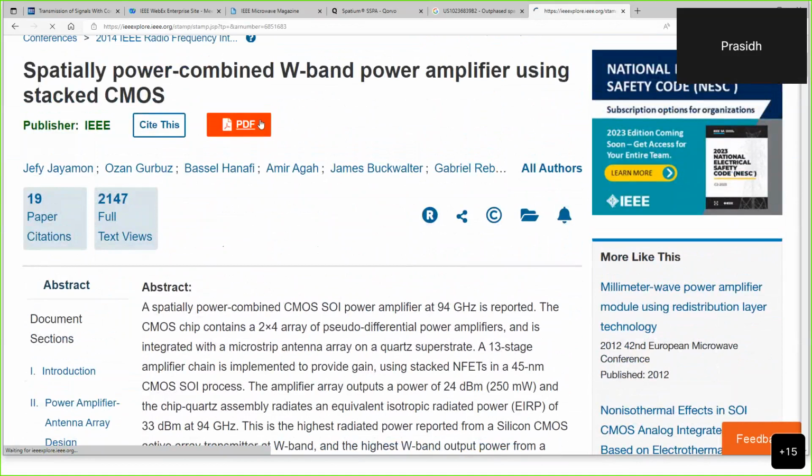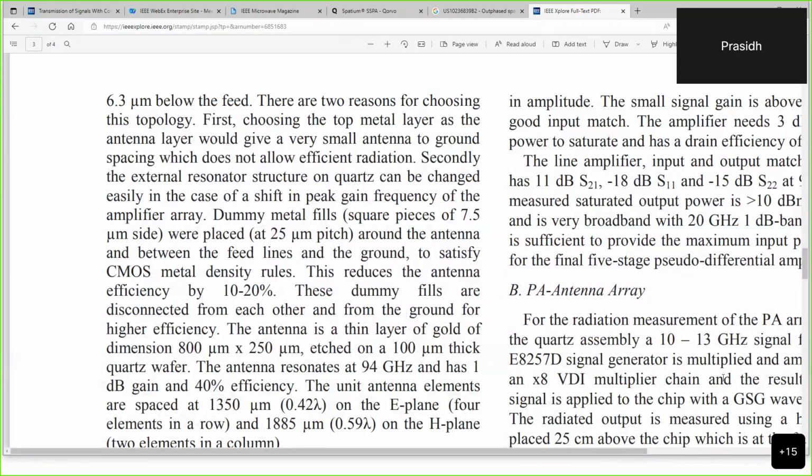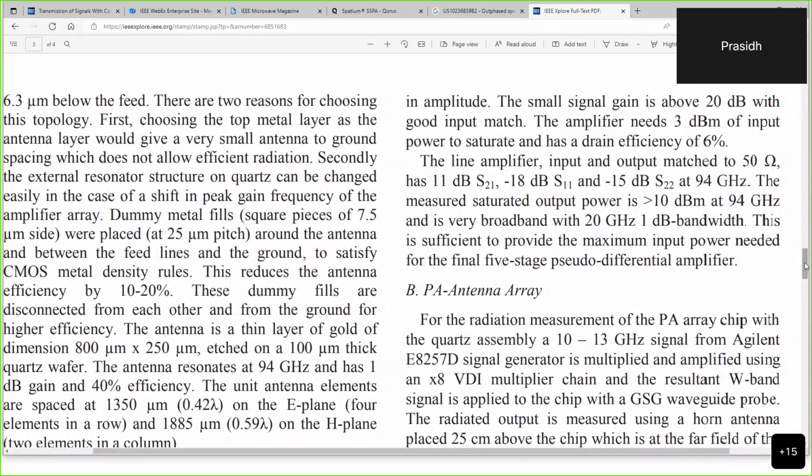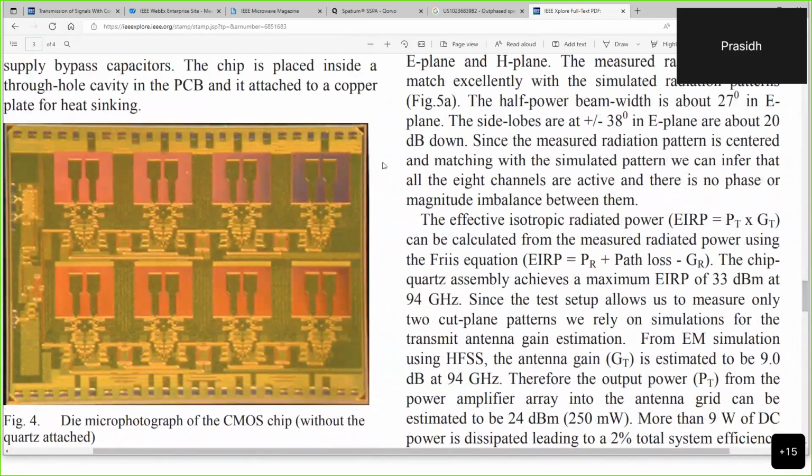Well, let's get back into the structure here. What one can see is just the power amplifiers here. Say each one of these is driven by a half bandwidth RF chain or a quarter bandwidth RF chain. Then multiple such chips, say 4 of them, can accomplish the task of generating or transmitting signals with bandwidths of multiple gigahertz, instantaneous bandwidths of multiple gigahertz.